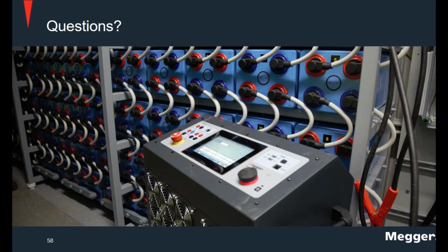So when you reinstall the battery, what needs to be done is it needs to be recharged first of all, and then kept on float condition for the recommended period of time as per the guides, depending on the type of battery that it is. After that, it is recommended to run another discharge test on the battery simply because it's been sitting there without any charge for 6 months. To find out if there has been any permanent loss of charge on the battery, you want to do another discharge test and find out the actual capacity of the battery.